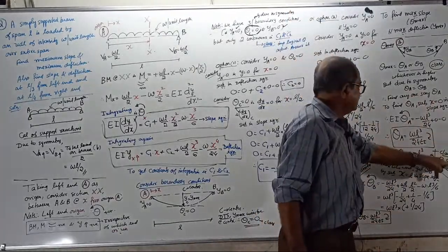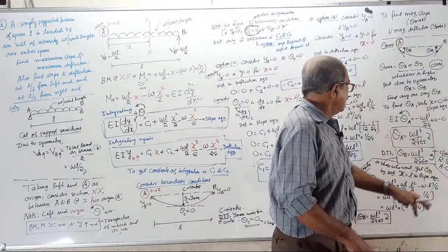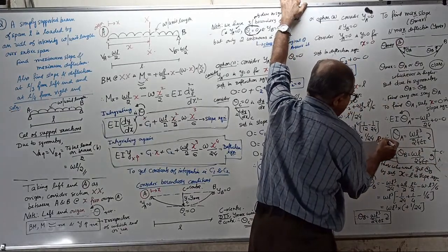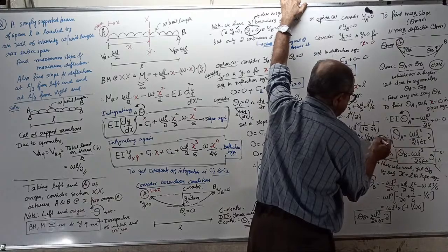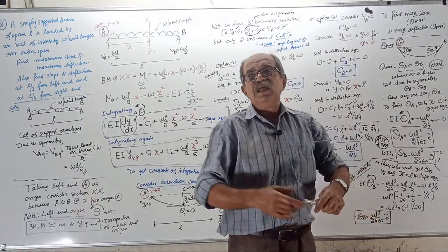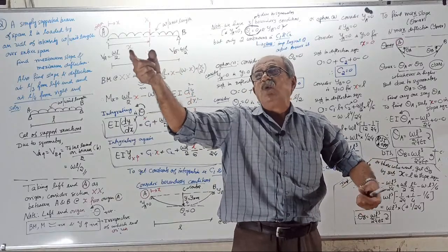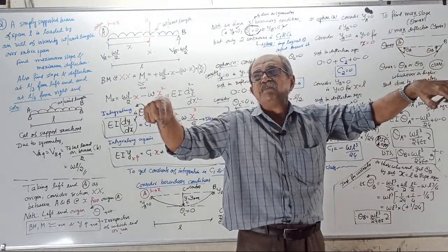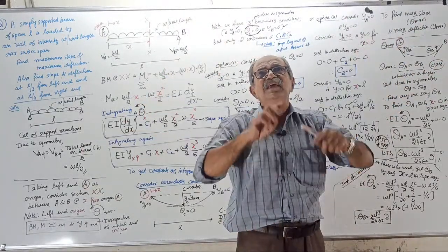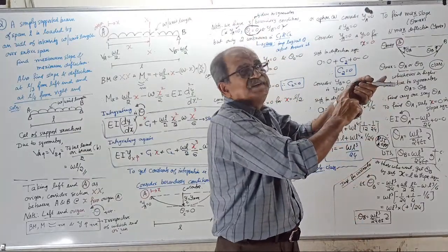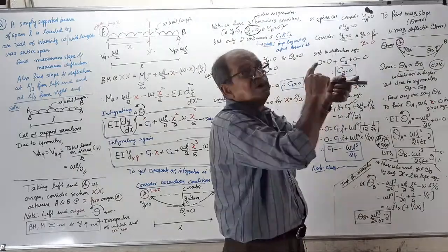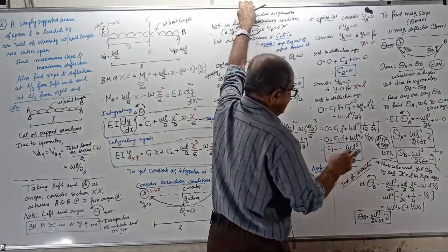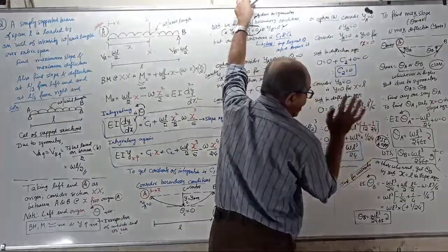Remember, class, make a note here: rotational symmetry is always opposite. It means if anything is anti-clockwise here, then due to symmetry it is clockwise on the other side. If anything is clockwise here, symmetry means it is anti-clockwise there. Rotational symmetry is always opposite. If a fixed moment is anti-clockwise here, due to symmetry the other side will be clockwise. If both are clockwise, it is not symmetry.